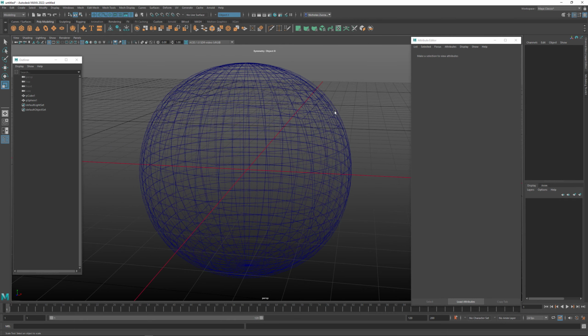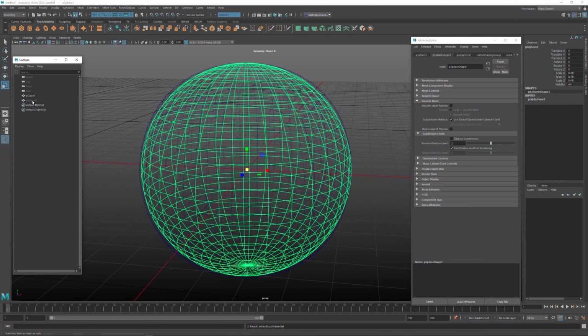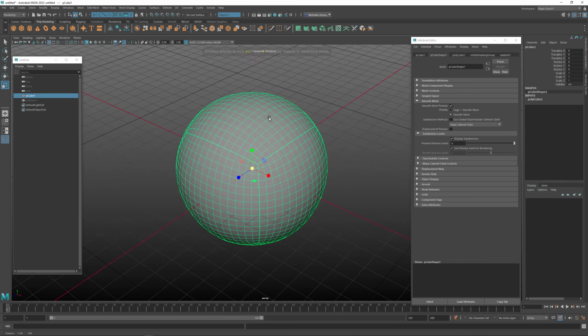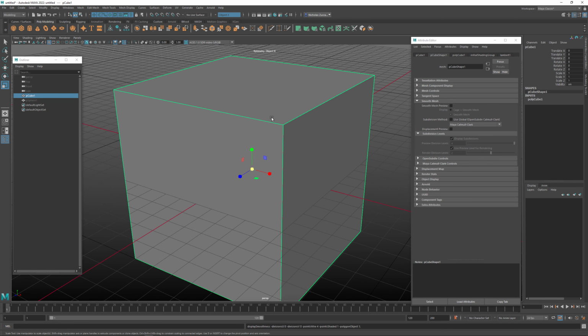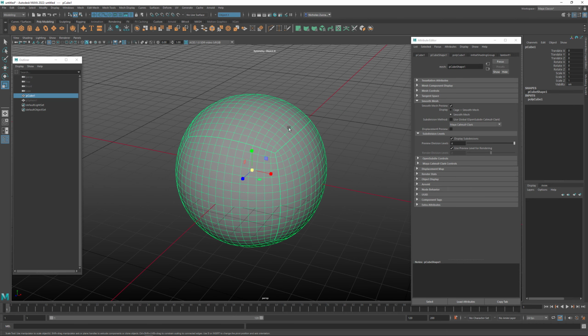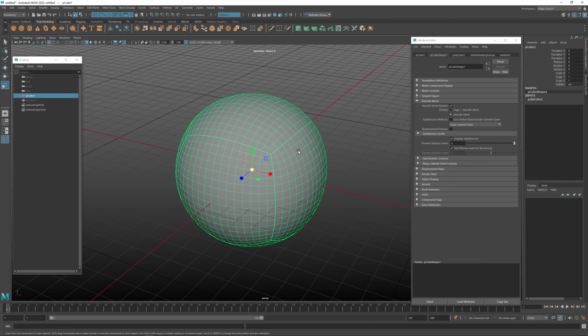And the other thing that we would need to do is, I'm going to hide this sphere real quick. We would need to take our object and convert it over to actual geometry. Right now, it's still just this cube. We tap 1, then we tap 3 for the smooth mesh preview. It's just in a preview mode, so the geometry doesn't actually exist at this higher level to actually manipulate it. So there's no way to kind of get to the vertices of this and manipulate it.